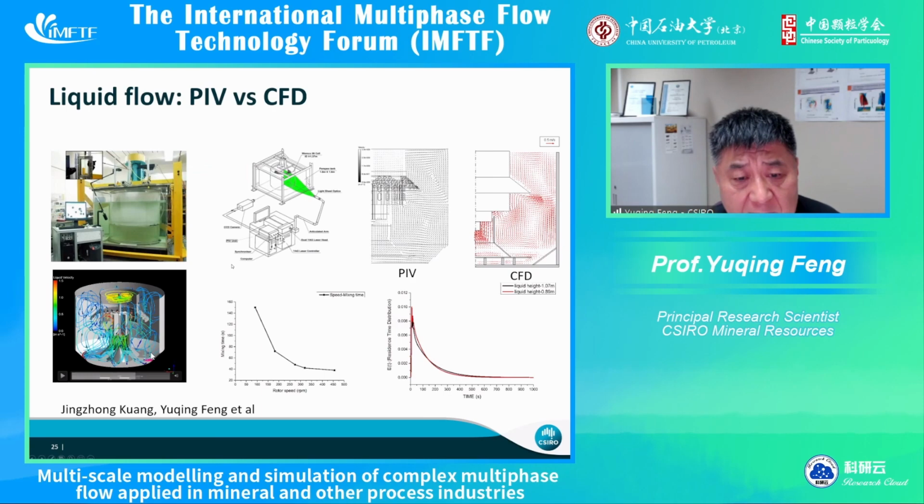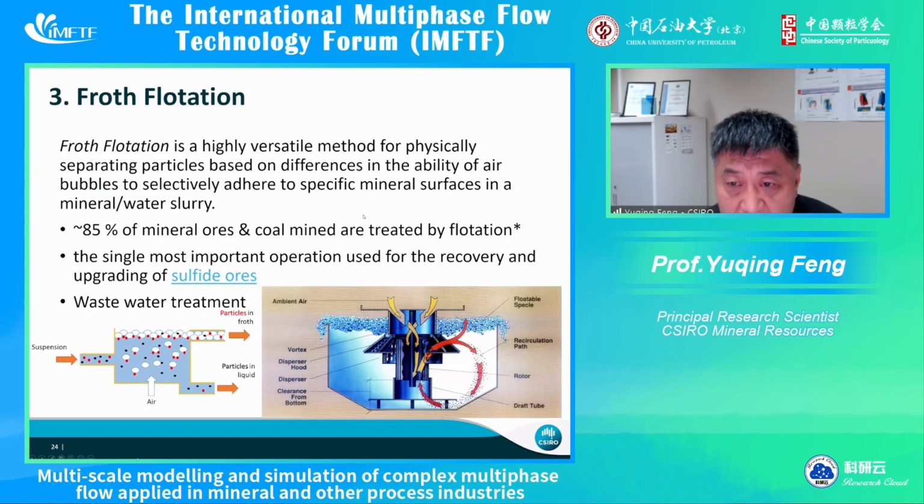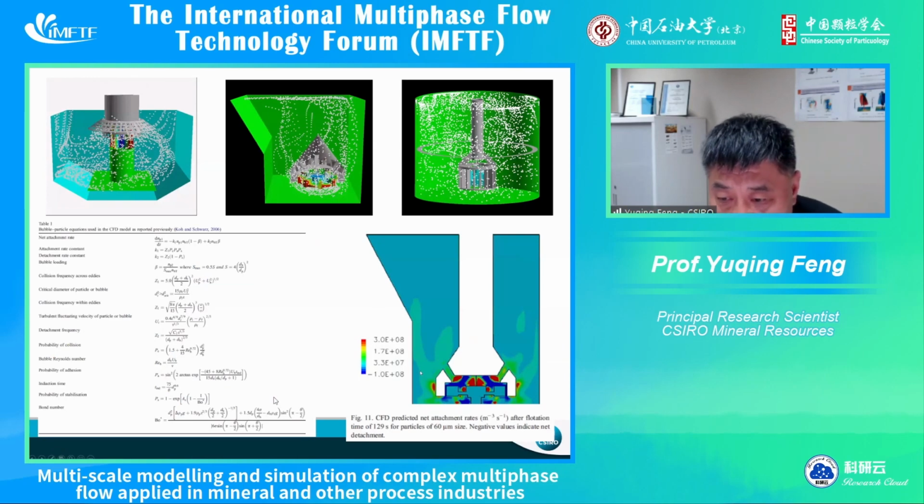Another is the recovery of the particle. How do we judge it? We link the model with the detailed model we develop. This is still the bubble and flow model. We link the bubble-particle collision efficiency to the bubble size and the turbulence. This is the big component. Then we use this type of model based on the macro, the local average turbulence, the bubble concentration and the solid contribution. We work out the particle collision efficiency and the collection efficiency, and this links together to work for different industries.